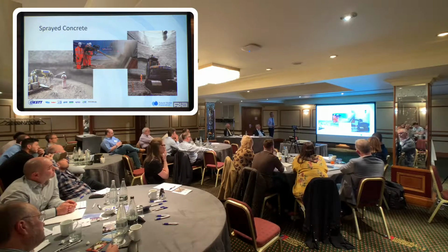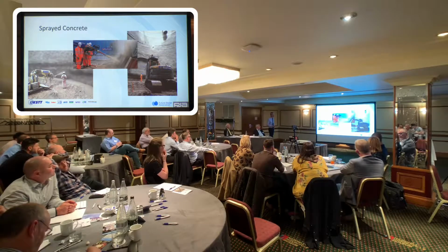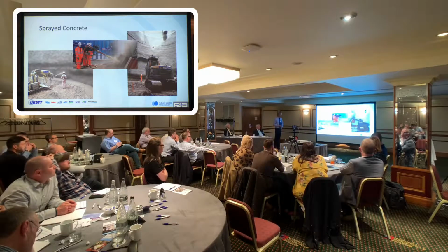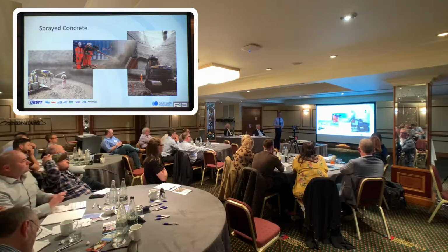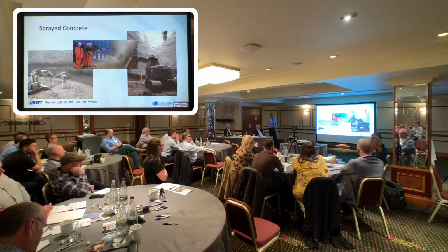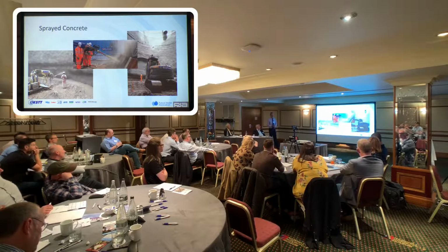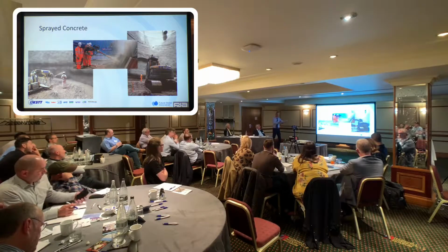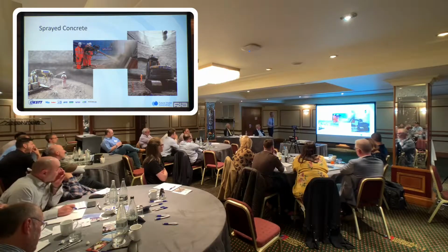Sprayed concrete is a fantastic method, but it does involve quite a lot of QA and QC. And this picture is an above ground test panel spray. So we're filling these little boxes with sprayed concrete, which are then used to test early strength gain, etc., to test performance before we actually use it in anger in the ground.